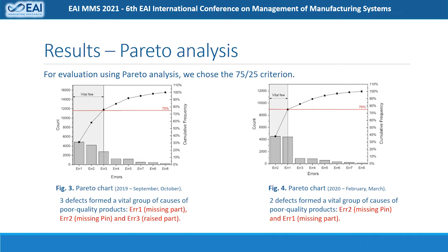In the case of error 2, the absolute number increased by almost 8% compared to the previous period. Therefore, for error 2, it has been proposed to add an in-circuit board tester control pin to check the length of the connectors. Adding this will extend the testing time, but will improve the quality of the supplied board.